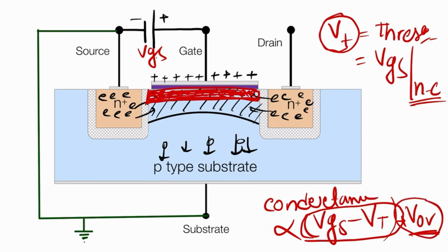Okay, so now you can easily understand how this N channel is created in a p-type substrate, right? As this N channel is already created, if we connect a voltage source to the drain to source terminal, then what will happen? A current will flow. So now I will explain it in the next image.